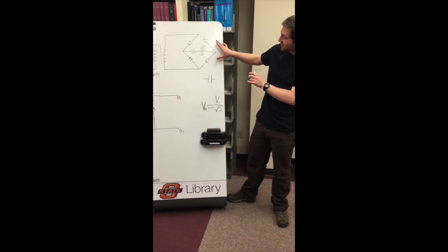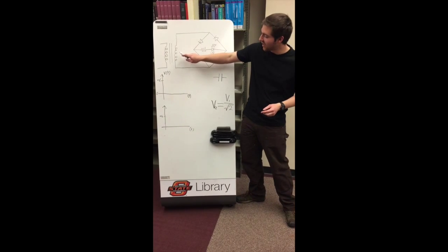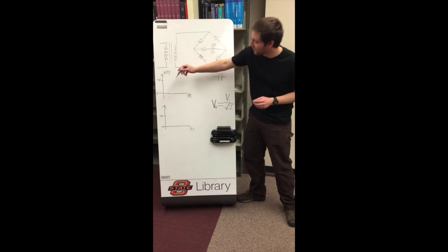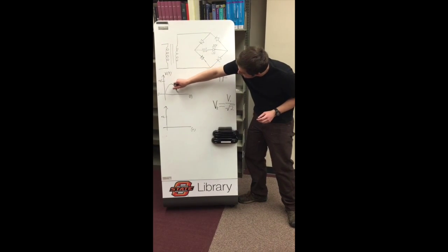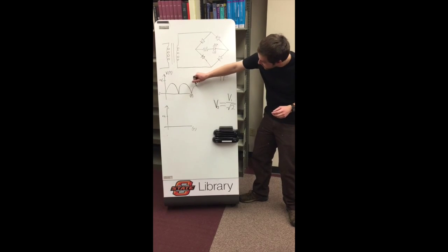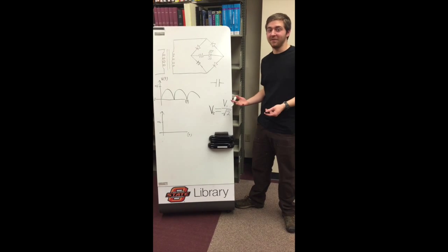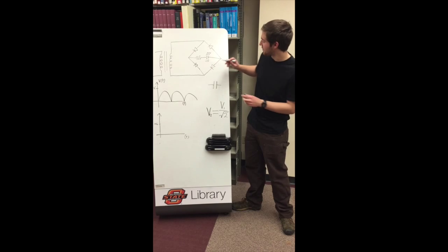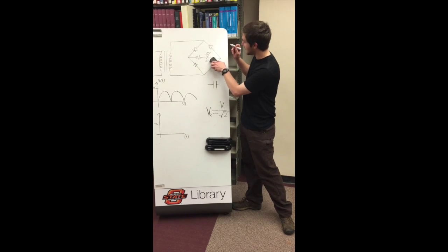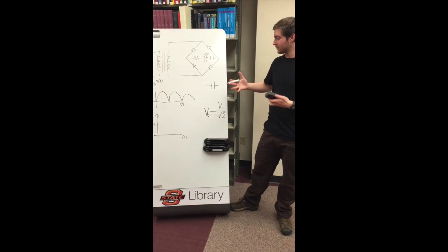Now, this configuration of diodes does give us a current in one direction independent of the current source. However, it results in a voltage function which is similar to the absolute value of a sinusoidal wave. While all the voltage is positive, it's not very efficient. Now we can use a capacitor to smooth this out. A capacitor is a device which opposes change in voltage.